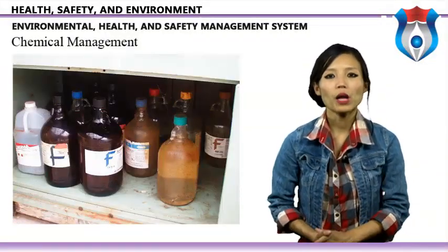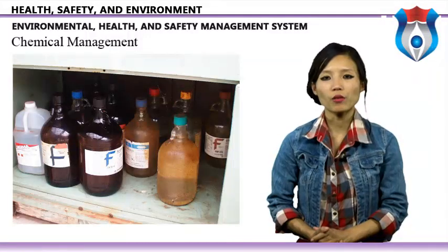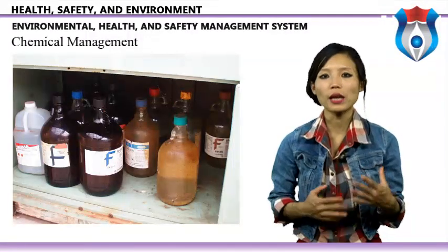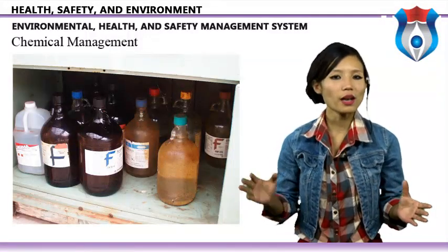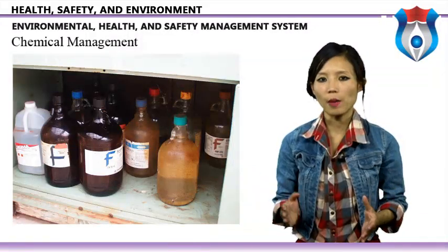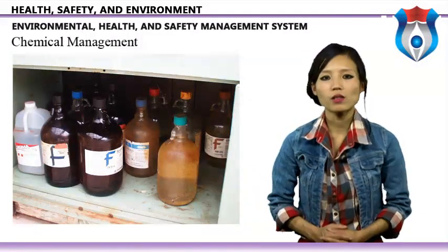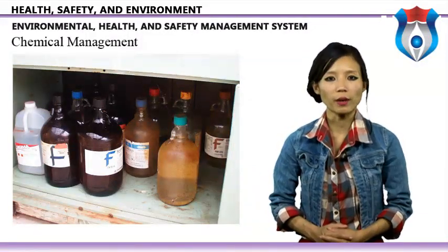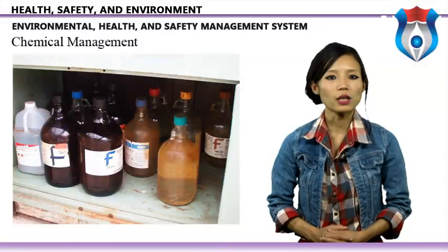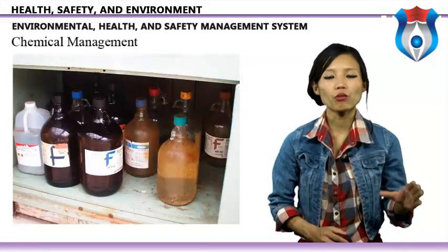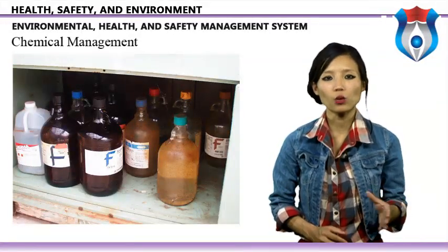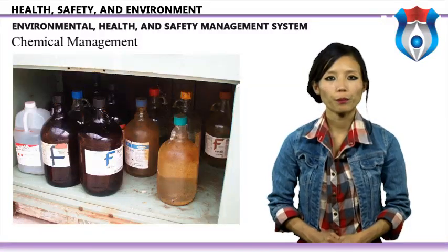Chemical management. Use chemical hazard assessment and risk management techniques to evaluate chemicals and their effects, and utilize the least toxic and hazardous chemicals considering persistence or bioaccumulation aspects. Use low toxicity lubricant additives to reduce the overall toxicity of drilling fluids where possible.